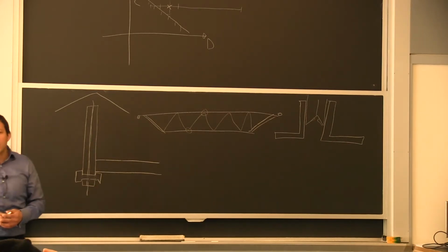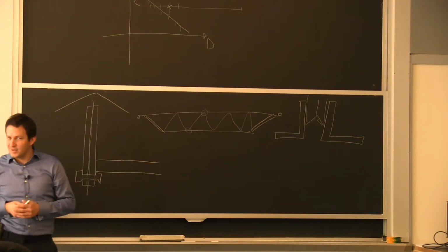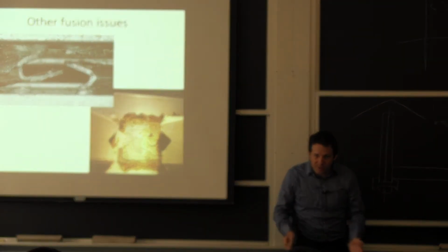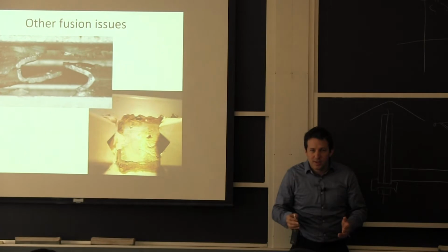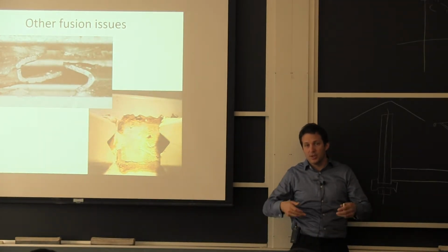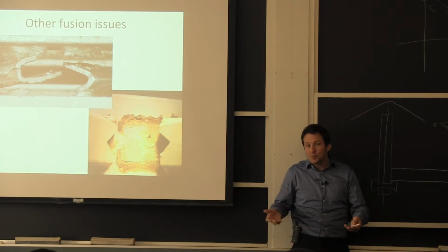Yes? Turn down the amperage on the motor so that you heat it up slower with that action. Yes, it just takes longer. Exactly. It is always the option of going slower and putting more heat. So you supply more heat and you provide less filler, essentially. At the extreme, if you think about TIG welding again, you don't provide metal.